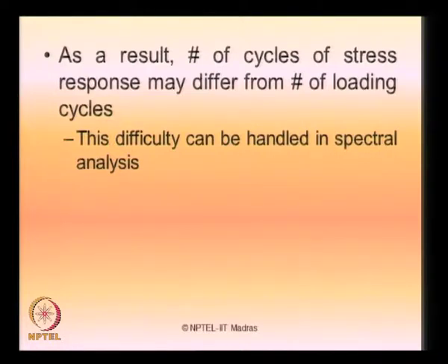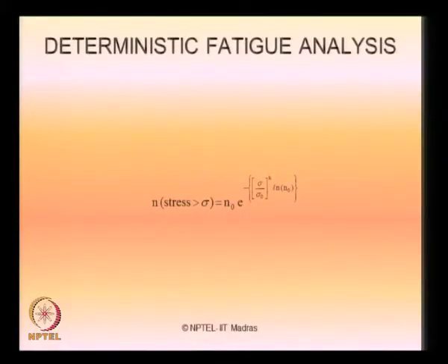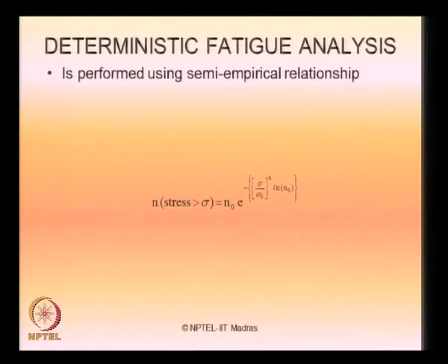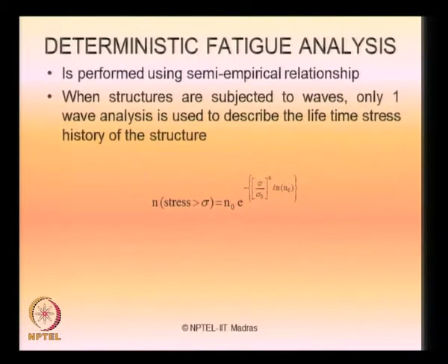This difficulty can be handled in what we call spectral analysis, because once you start playing with the selection of the time domain where your structure is operating, and in that range you want to look at the fatigue damage, then obviously you cannot do it with the time series of stress cycle ranges. You should look for spectral analysis. So, let us talk about deterministic fatigue analysis. It is performed using a semi empirical relationship. When the structures are subjected to waves, only one wave analysis is used to describe the lifetime stress history of the structure, that is assumed.